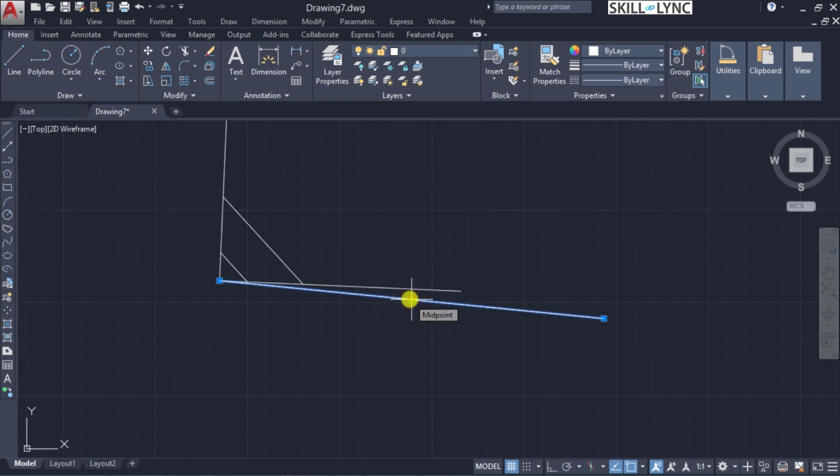So the next option we have here is a kind of hidden command. After selecting this, the default command is stretch or move based on the selection you have, but by pressing the space bar, it will go to the next point. You can see the next move point that is required, and also the angle of rotation that you can specify. For example, for a rotation of 45 degrees, once you position the next rotation point, you can get the rotation angle after cycling through the space bar. So now suppose the angle should be 45, then it's also affected.